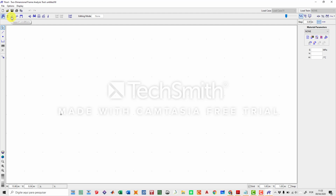Here on the right part you have support conditions. If you click on each one of the subjects, the right part is going to change. So here are the support conditions. You can restrain the displacement in X, Y, and the rotation about Z. The Z axis is the axis coming out of the screen, let's say. You can also put springs into your restraints, for example, to simulate a spring for foundation design purposes. On the right part, you will have the connection conditions.